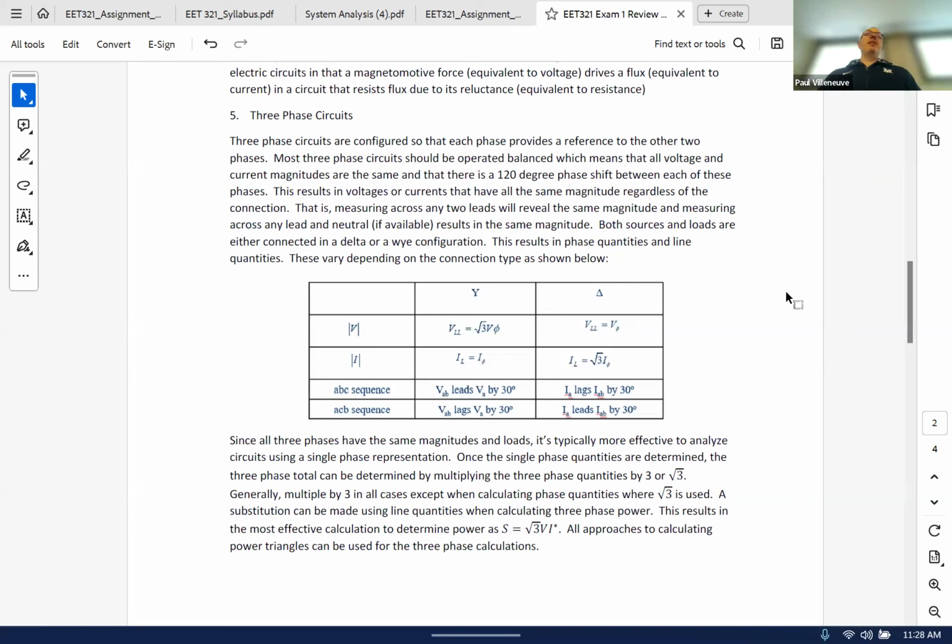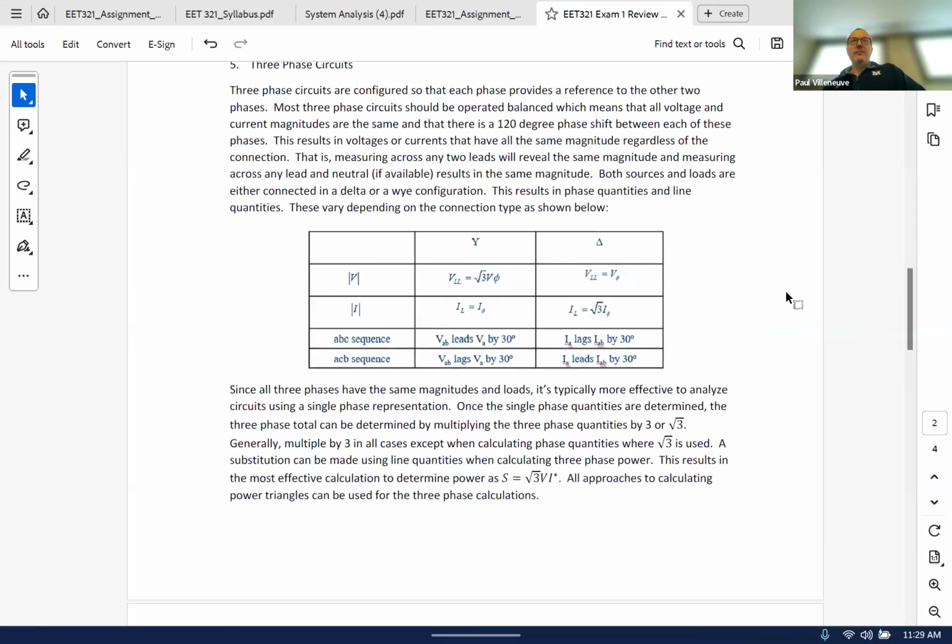Same thing in ACB, and there are some ACB cases, not many, but when you have phase A, then C comes along, and then B. Remember, phase ABC or phase ACB are just what the end customer has called them. They might say this is ABC or this is ACB. That's just the convention that they use, because the winding that comes from the generator manufacturer or the generator itself is just 3 wires. It says H1, H2, H3, or X1, X2, X3. It doesn't say ABC. You get to put whatever one you want on. So there's no stipulation.